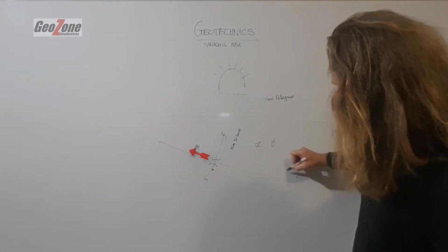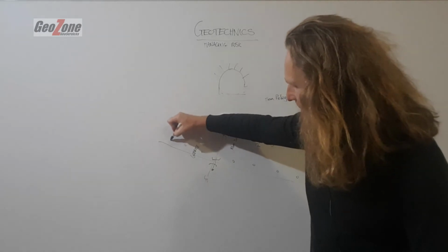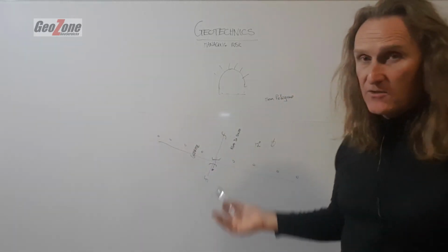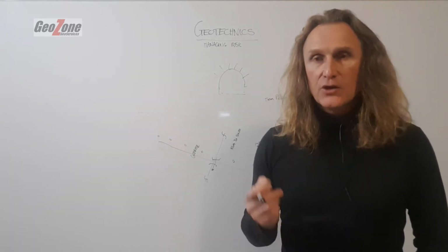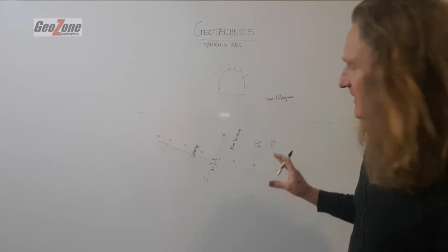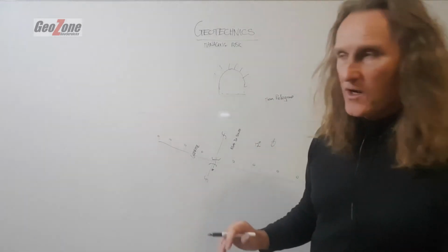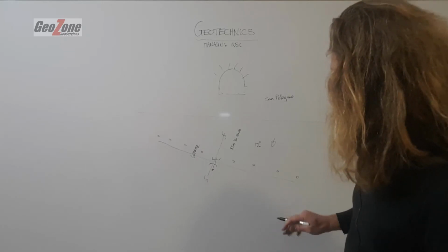But they had drilled boreholes all along this tunnel. So when they got here, they had some idea of what to expect. Of course, there's also the geological maps to be consulted and all that historical work that can tell you so much, even before you start thinking about drilling boreholes and doing that kind of work. You go back to the databases that are available to you.